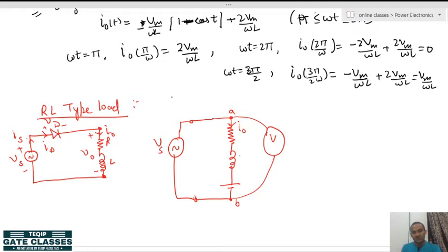This is the source voltage. Now if the current is flowing through this circuit, and I ask you what the voltage value will be, you will simply say that the value of the voltmeter will be equal to Vs. Whatever the Vs value is, the voltmeter will read that value. Why? Because you will see that the AB terminals are in parallel with the source.